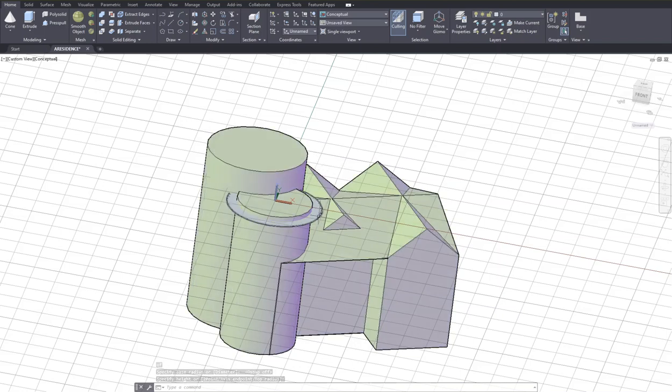All right. So I'm going to just take this back, and the object snap, even though it's turned off, 3D object snap got in the way. So I'm going to just simply select this entity, the cone, erase it, and start it over. Again, cone command is here. Computer is asking me center of. So I'm typing CEN for object snap, moving my cursor close to this edge of the cylinder, and center is selected.